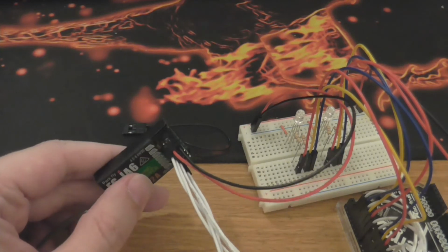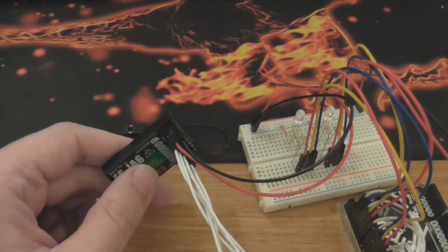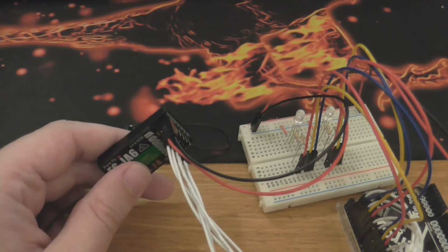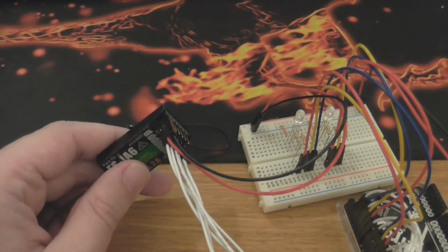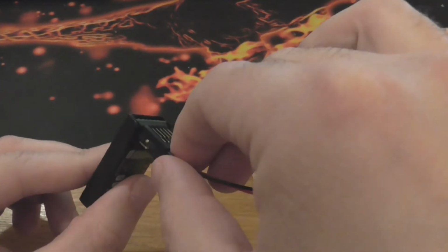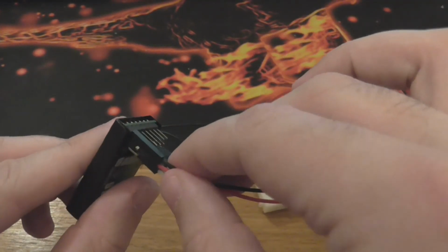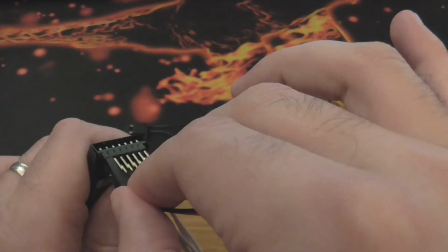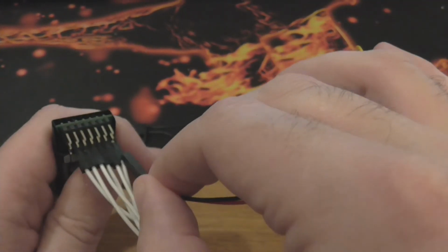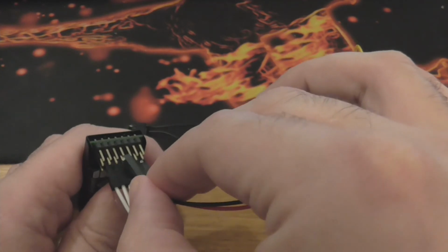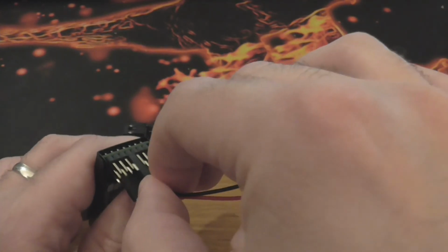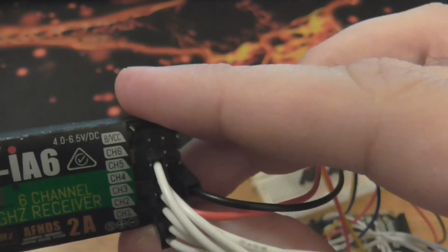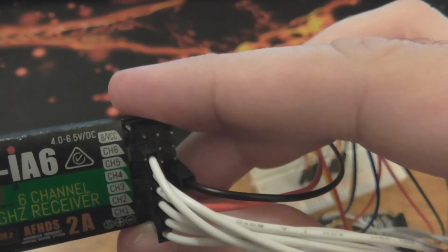One note that I want to mention before I actually turn the transmitter on and start reading from it is how to actually connect the transmitter to the receiver. So here I've got the receiver, and these 2 power lines are actually used for something else as well. So I'm going to move these power lines to a different channel entirely. And then if you notice the top channel there where the power normally goes, it says B/VCC.